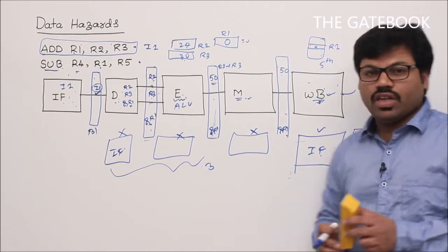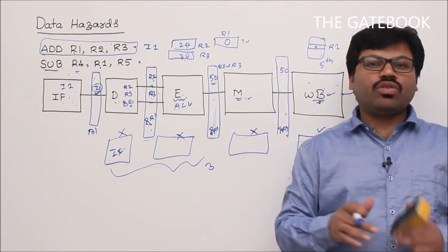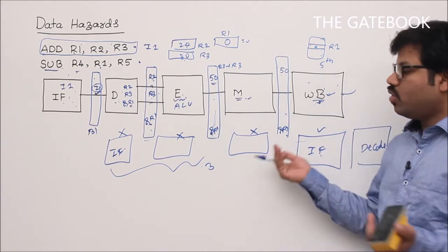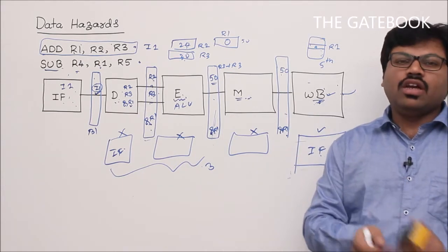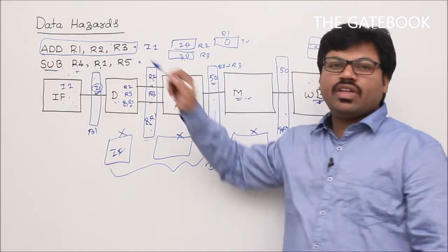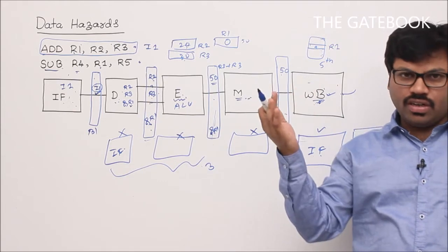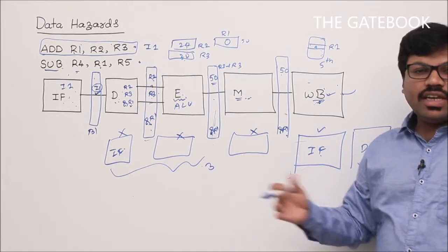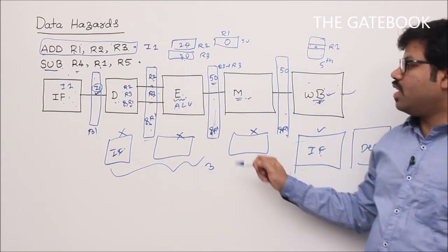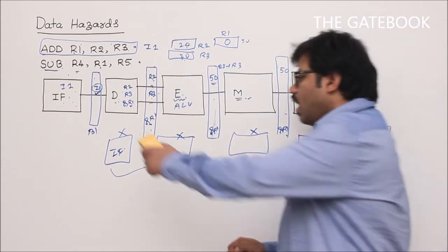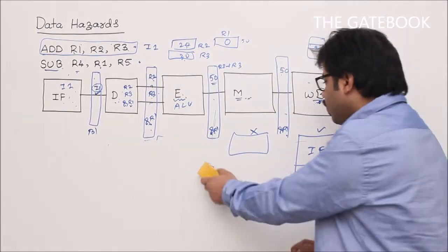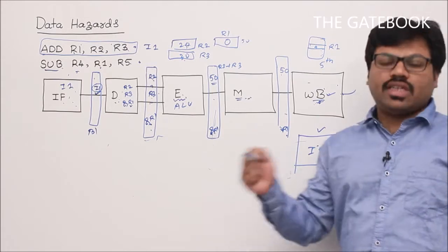So that's why I want to tell you that data hazard is going to affect the performance of the pipeline. Then sir, what to do? What are the solutions here? Solution number 1, the easy solution. Somehow you detect that there is a dependency between the instructions at the software level, and you design your hardware in such a way that whenever there is a dependency, the instruction is appropriately stopped. That means your hardware should be stalled in such a way that the next fetch should not be done. The next fetch should be done here. In such a way we have to design the circuit.